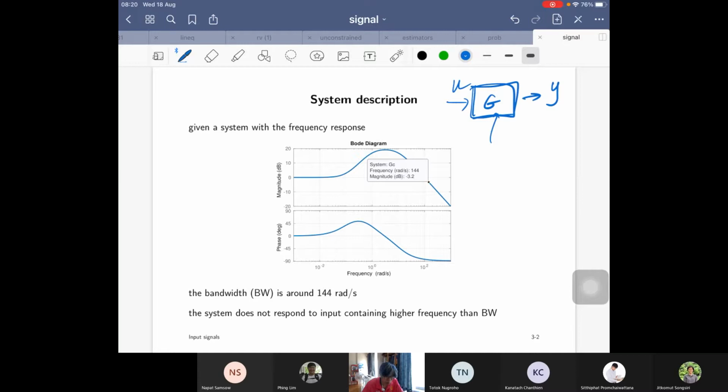Okay, so by doing that, let me represent it by having this frequency response as a relationship between u and y, represented in frequency domain. Of course, you can obtain this graph from the experiment. Okay, when you apply u as a sinusoidal signal at a certain frequency, and then you measure y, you get 1 point on the Bode plot. Okay, and you vary the omega for a number of frequencies, and then you get the whole thing.